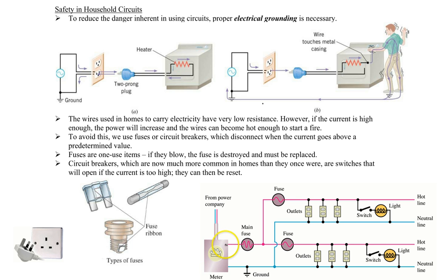That main line that's coming in here has a fuse, and we'll talk about a fuse in a moment. And then you'll see that all these outlets and all the devices that are connected via these outlets are all connected in parallel. We'll talk about what a parallel circuit looks like in comparison to a series circuit a little later on. But in your typical household, you may have anywhere from 4 all the way up to possibly 30 different branches. In this picture, we only have 2 branches, so you have maybe one room with these 3 outlets and another room with these 3 outlets. But your household may have a lot more branches, obviously.